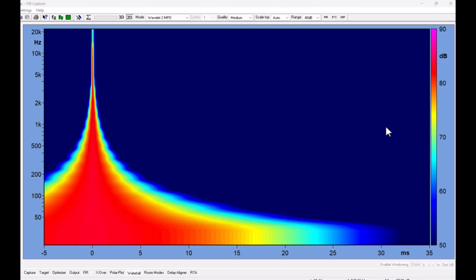It's not useful to make a linear phase system for live PA systems, because it requires an FIR equalization, which must be very long, about 50 to 100 milliseconds, and you can't allow for that processing latency in such a system. So the solution is to make a mixed phase system, and I will come back to that in a presentation of FIR capture.